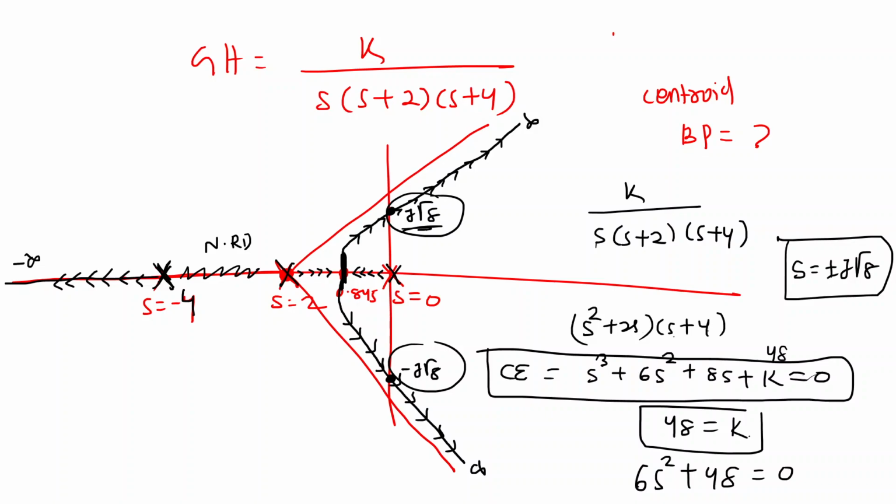Yes, sir. That is done with the Routh-Hurwitz criterion. If it is a fourth order system, use the RH criterion. If it is not a fourth order system, then simply apply the third order system property and answer it in very little time.